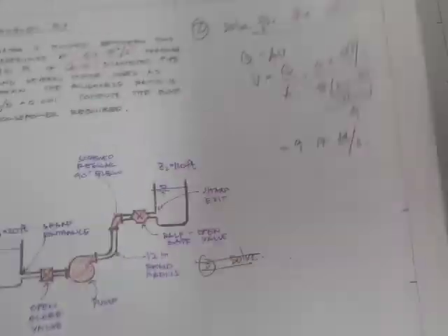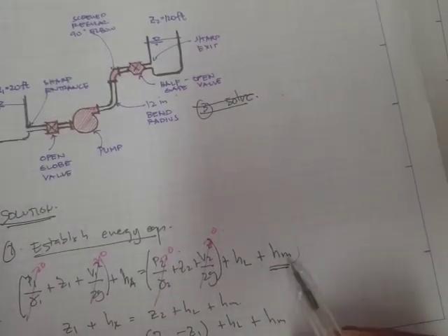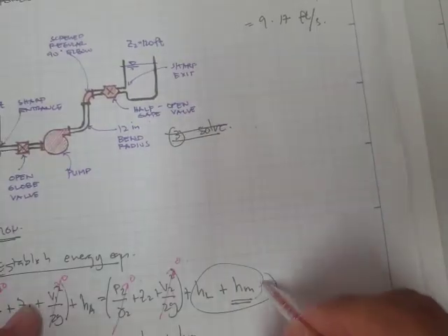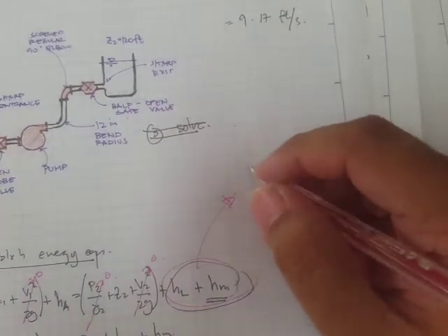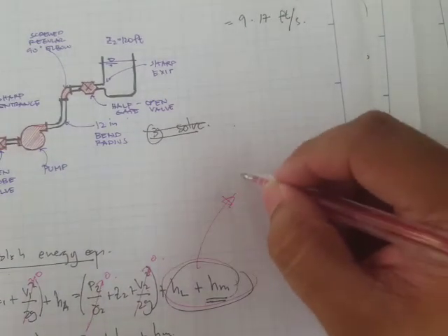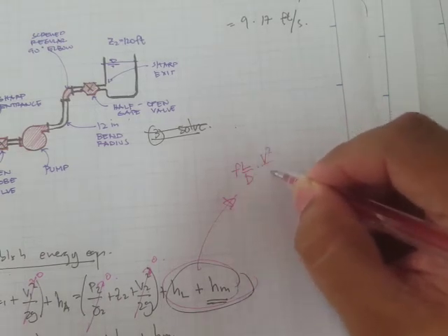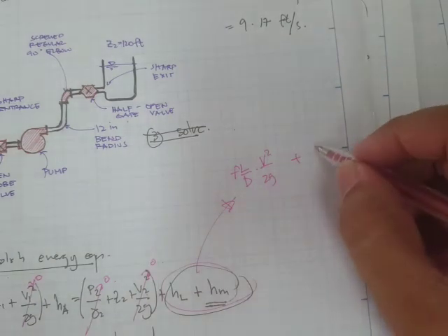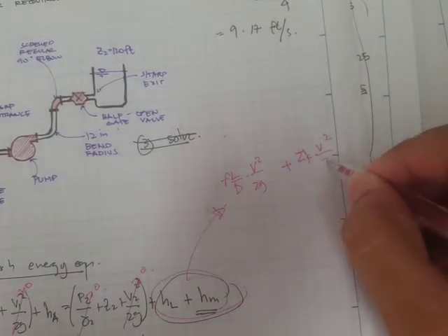if we have to include the minor loss, then we just have to include another term right here in the energy equation. And sometimes you can actually express this, I think you can also do this, since this is fL over D times the velocity head, V squared all over 2g, and this one is simply summation of K times V squared all over 2g.